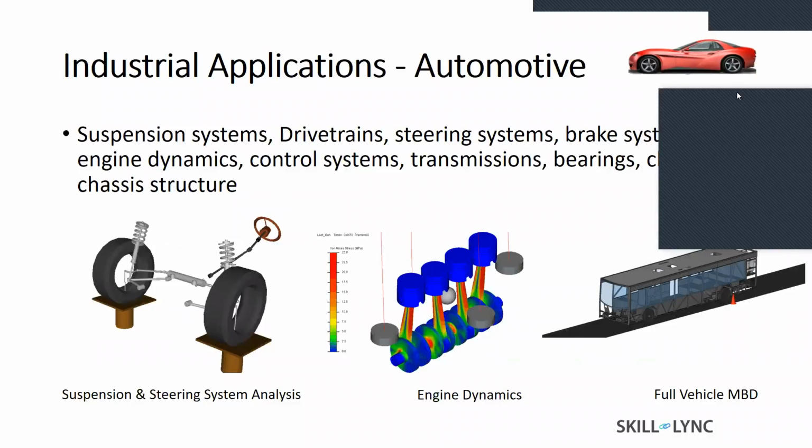Yes. When you solve a problem using MBD and FEM, you can expect the same results, but at a loss of accuracy, because you can model accurate models even in MBD using flexible bodies. I'll come to that in the later part of this presentation. You can do that, but it is a little more complex compared to using rigid bodies. When you're trying to run a simulation and get first-hand results, it's always better to go with MBD, and then you can deep dive by using your FEA.